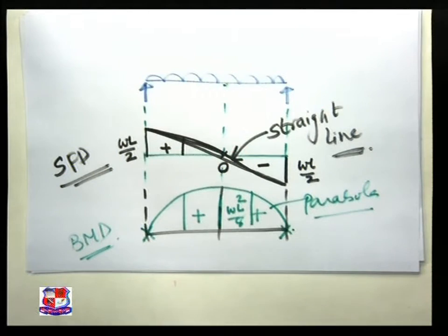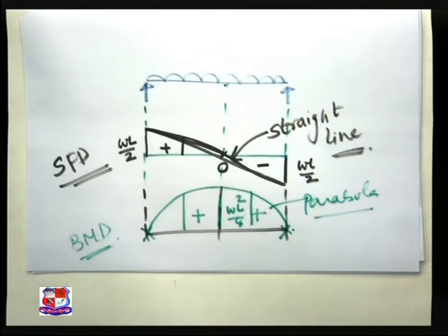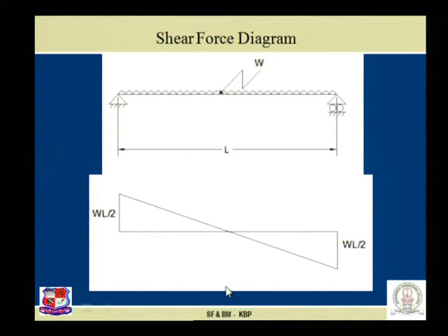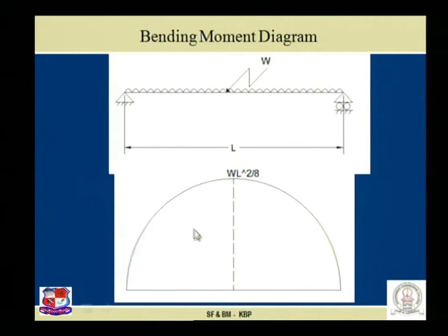So let us revise over here, or let us find out the conclusion. See the figure over here. When there is a beam with the UDL, the BMD variation is given by a parabola. WL square by 8 is the value for a simply supported beam.